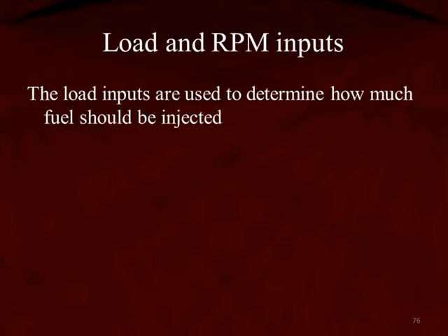For example, the load inputs are used to determine exactly how much fuel should be injected. That would be the injection on time. These load sensors report to the computer how much the driver's requesting. Are we going up a hill? Are we pulling a trailer?